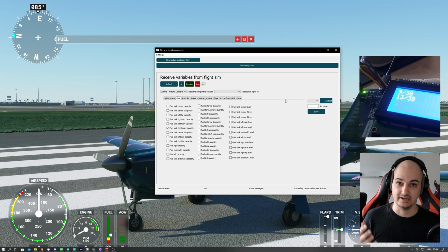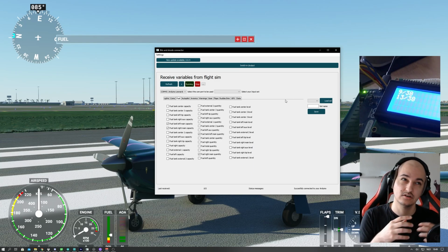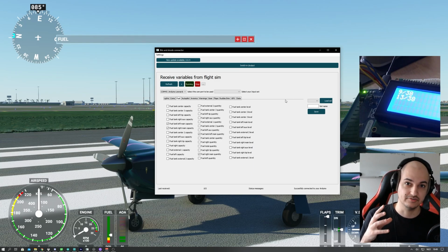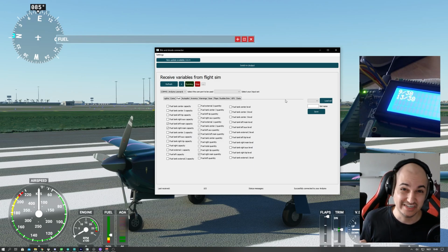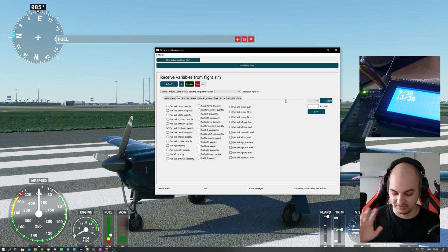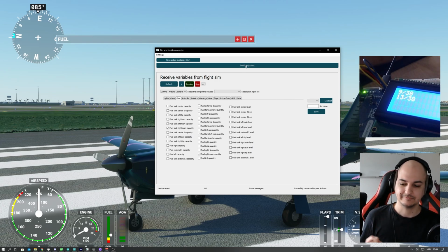And from there on out, you can build it out to a TM1637 or a MAX7219. I always get confused if it's 7219 or 7129, but it doesn't matter, either one of the screens. I've got a video about those coming up as well. I love the TM1637 because it's so much easier to use, but that's just me. It takes a bit more pins than the other ones, so it all has downsides, but it's available right now.